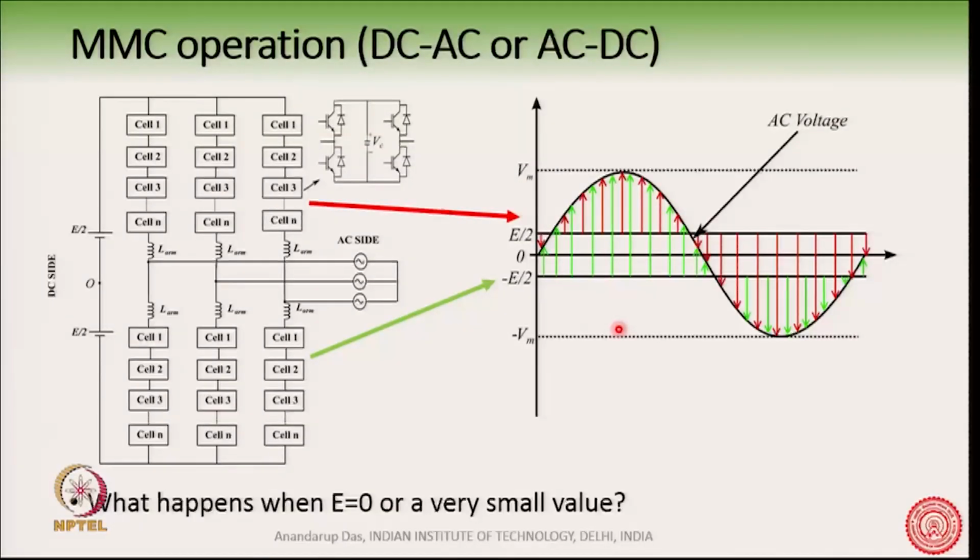In fact, the arm voltages during this condition are shown here on this diagram, and you can see that the converter can still work during this short circuit condition. You can think of the arm voltages during this time as something like a back EMF.